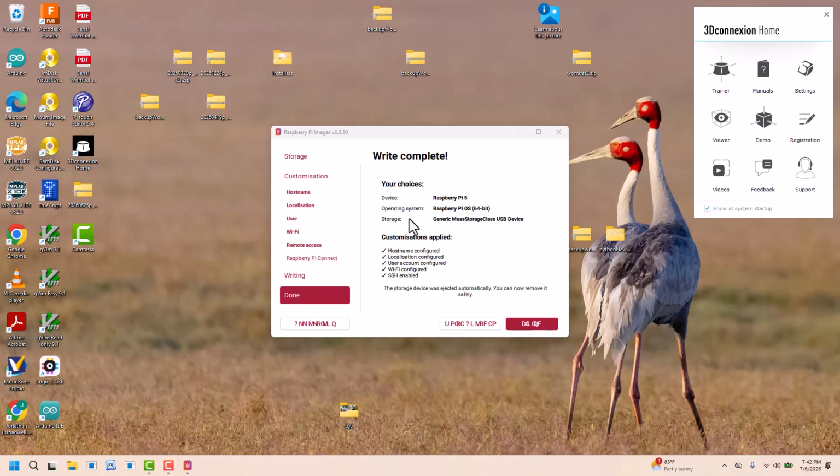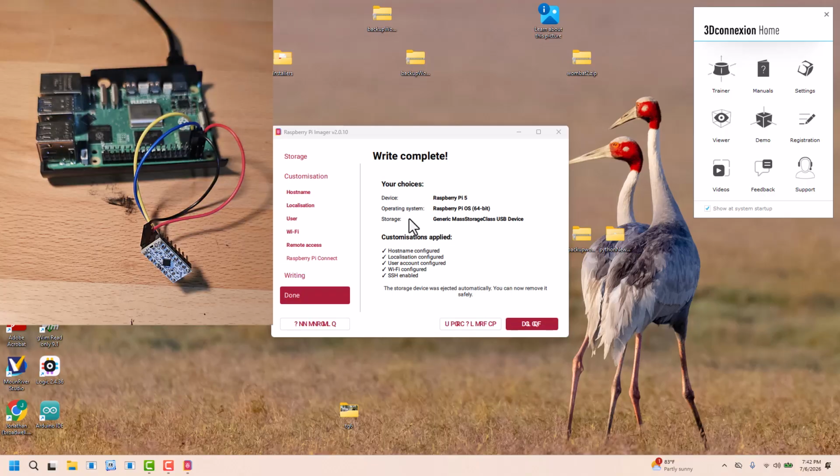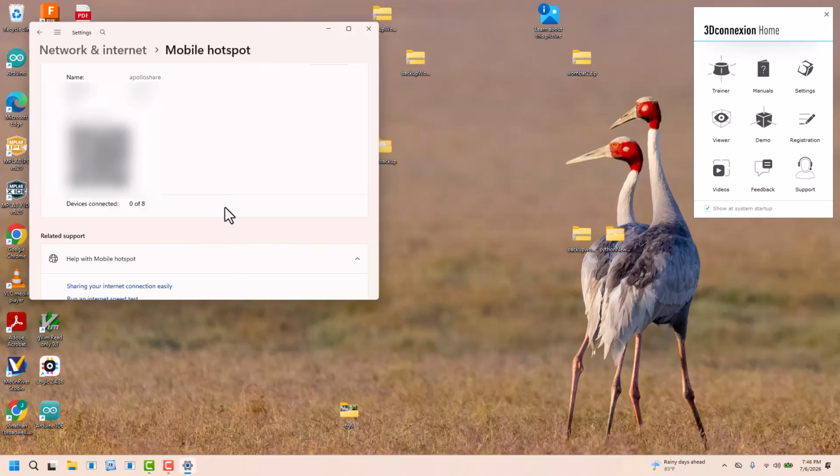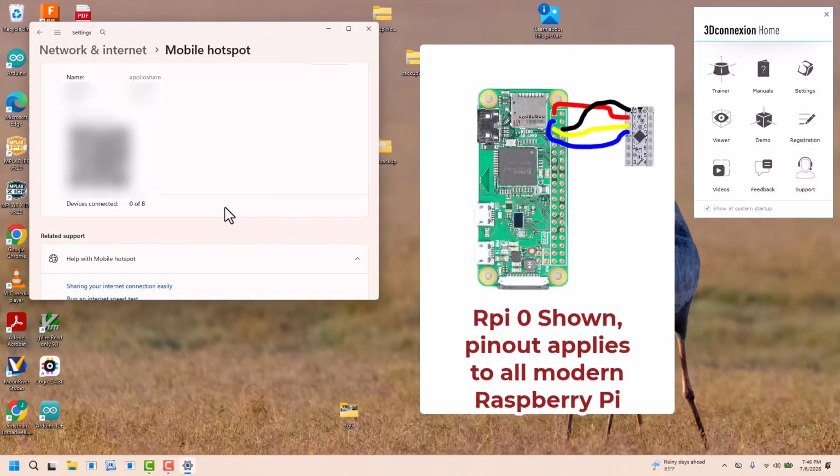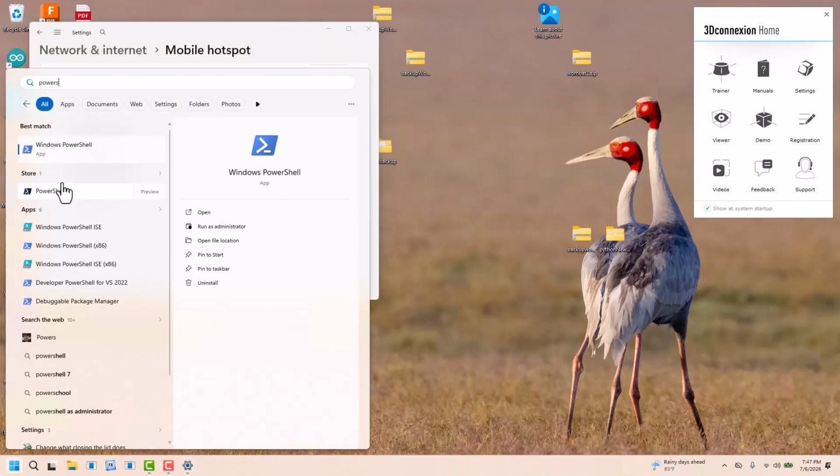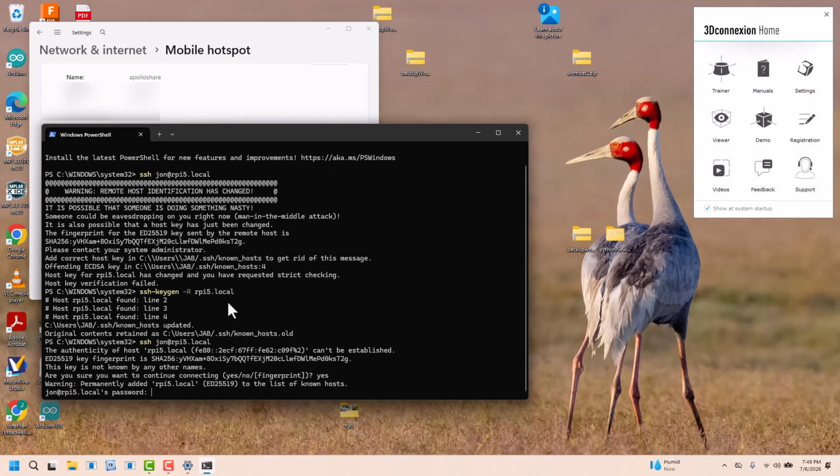We are connected to a Serial Wombat 8B, and it is connected up to the 3.3 volt line, the ground, the SDA, and the SCL. And on the Raspberry Pis, the SDA and SCL lines already have pull-up resistors, so we don't need to enable those on the Serial Wombat chip board. So let's SSH into the Raspberry Pi now.